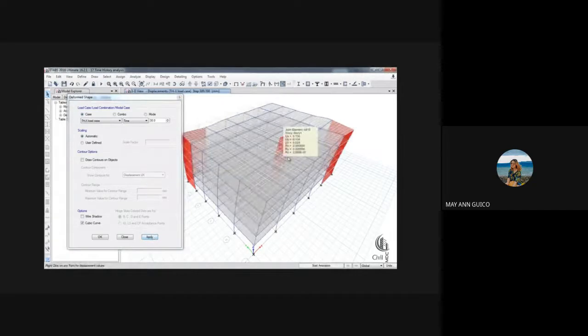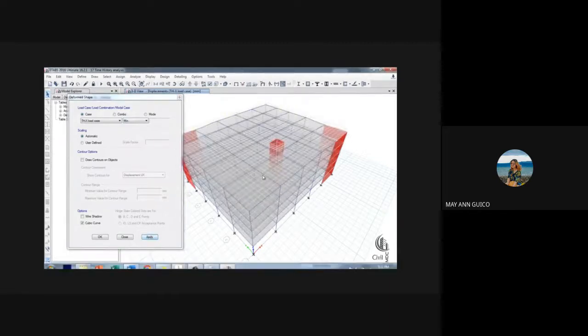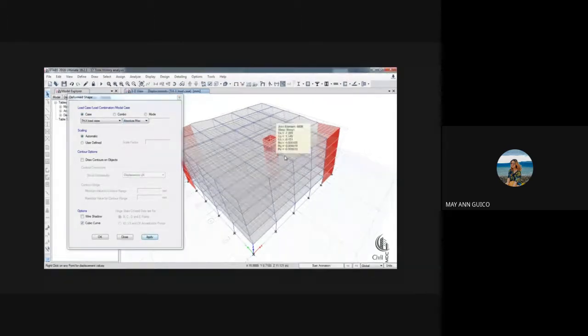Okay, now the beam is deforming. So we can also select the absolute maximum or absolute minimum. For example, here is maximum, apply. So that's the maximum deformation. Similarly, minimum. Okay, so that's coming towards my side. So here absolute maximum. So you can see what the deform behavior is at any time step.